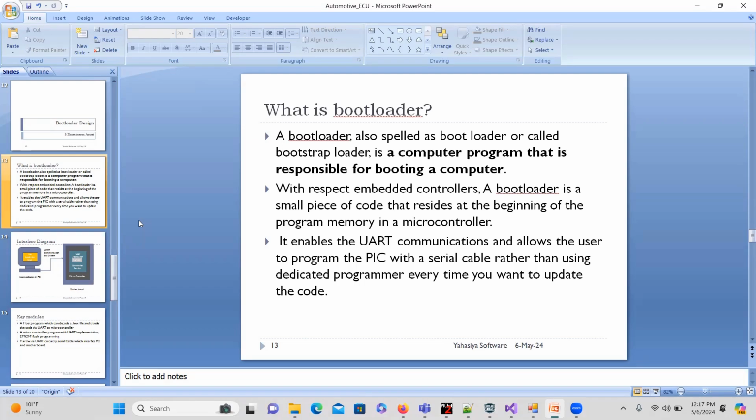The people in the automotive industry use something called the UDS spec, the diagnostic spec. I believe we have explained in our traditional sessions about diagnostics that diagnostics can be used for flashing the software. So the diagnostic layer itself acts like a bootloader in automotive ECUs, because using diagnostics you can flash the software. You can transfer the code from the external world to your microcontroller. The only thing is your diagnostic should be flashed at the beginning. That is the first software that should be available in the microcontroller before you flash your user application.